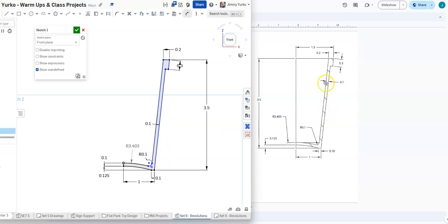Now we're going to roll in here and get that. We did that, so we have the thickness of the foot, we have the outer diameter. Always try to make the dimensions neat. We have the radius, we have that radius, we have the radius of the thickness of the wall. We have the height of the flange, the width of the flange, we have the height of the cup, we have the thickness of the flange, and we are only missing right now the radius of the rim of the cup.